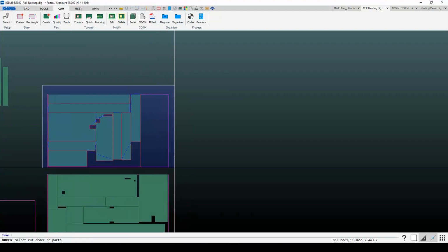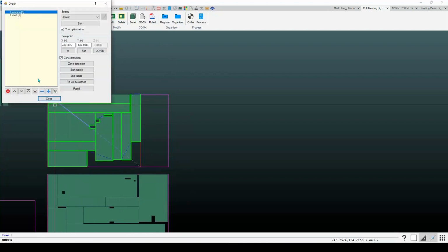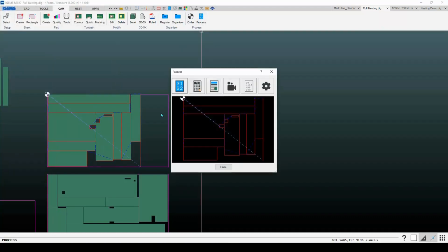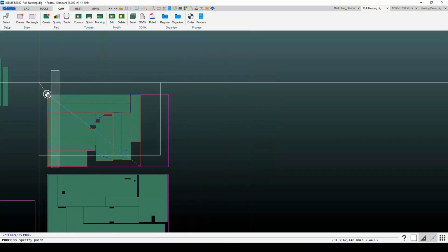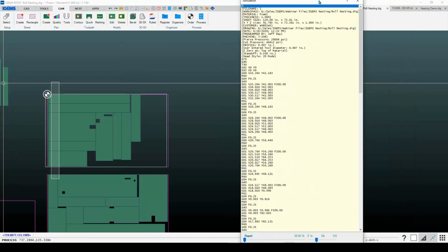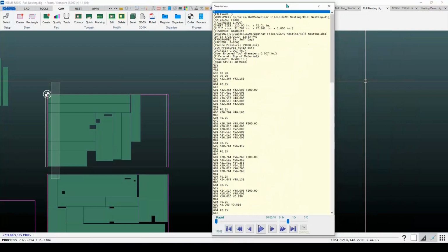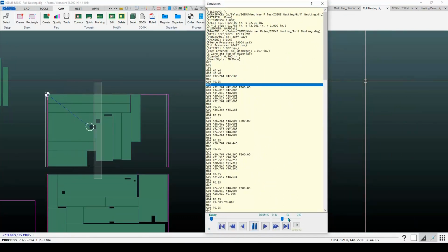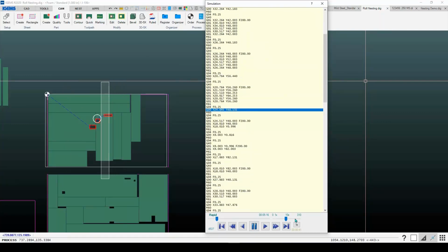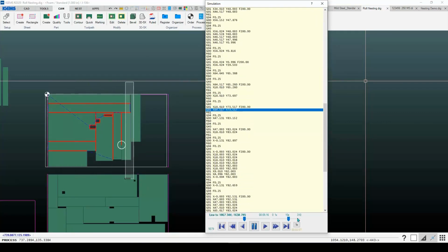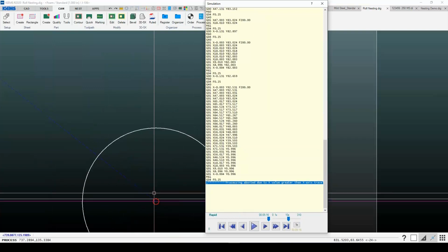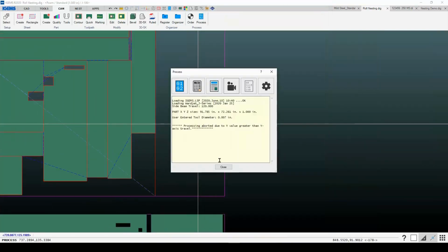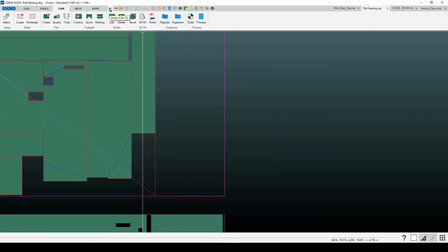So if I add my zero point on here for my sheet, it's got the common cuts that it'll do, and then it'll do the cutoff. Let's take a look at what this is going to do in our simulation. And let me resize this here a bit. So all of those are common cuts. And then I drew my line, I guess, a little bit too long there because I had that error message, but at this point here it would then cut up across that point there. So let me change that line here a little bit.